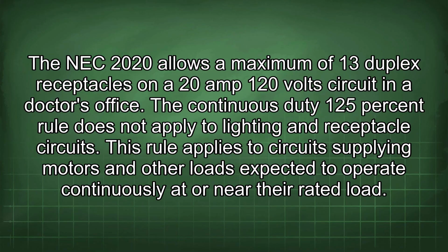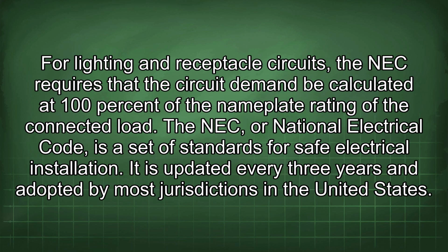The NEC 2020 allows a maximum of 13 duplex receptacles on a 20 amp 120 volt circuit in a doctor's office. The continuous duty 125% rule does not apply to lighting and receptacle circuits. This rule applies to circuits supplying motors and other loads expected to operate continuously at or near their rated load. For lighting and receptacle circuits, the NEC requires that the circuit demand be calculated at 100% of the nameplate rating